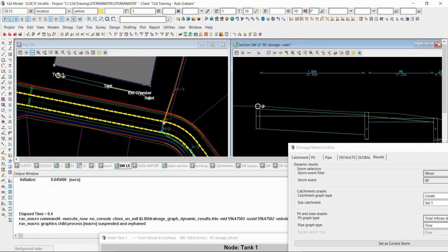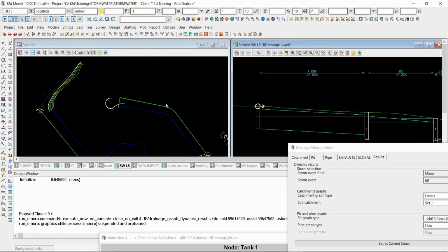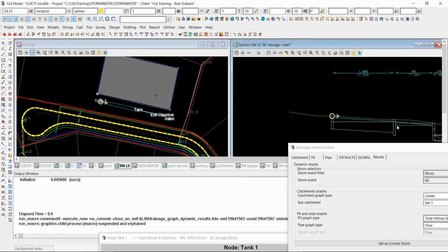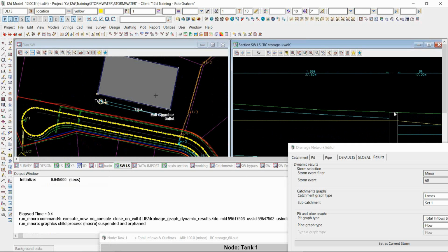It'll take slightly longer, of course, if I was solving for the entire network here, which is why I isolated it for this presentation. The second one is about diversions from here. I've got 3 flow paths between the control structure at the end of my tank down to my outlet pit. But that's only 3. I could also have water bubbling up out of my grate, and then I would have bypass on the surface, and I could have bypass channels to take the major flows away. I could have the water going to a separate open stormwater pit if I wanted to do water quality. It would all be just about adding additional links.